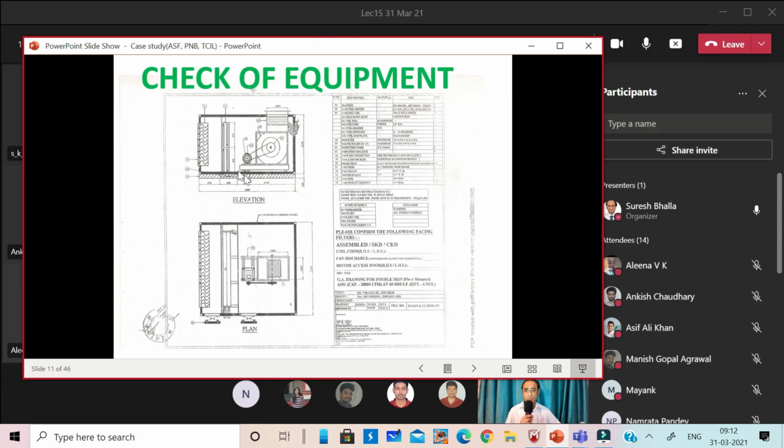So the equipment involved this kind of rotating parts, where there were two rotors, and they were connected by a belt kind of mechanism. And when we went through the drawings, we found that their operating frequency was 849 RPM as per the drawings, as per the specifications, and this is something like 14 Hertz, which is very close to the disturbing frequency which we had captured.